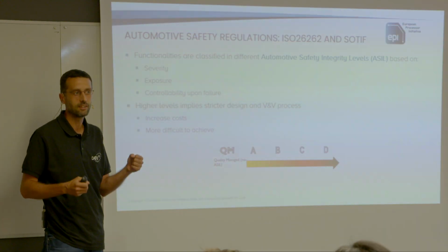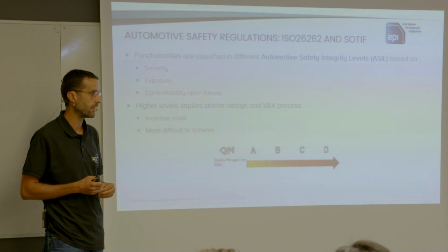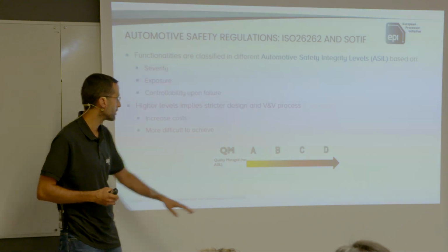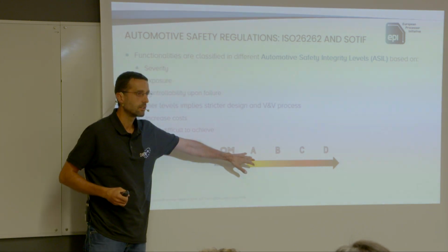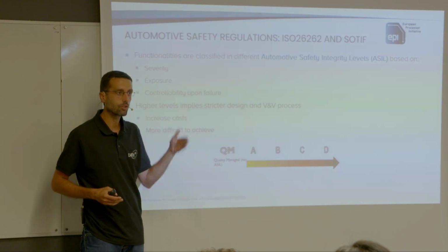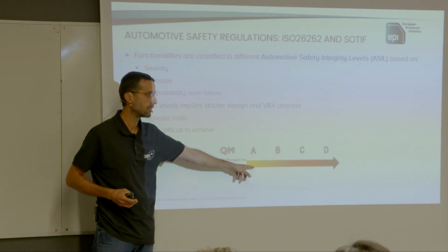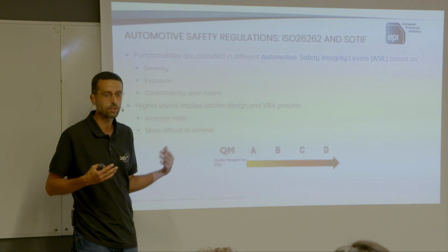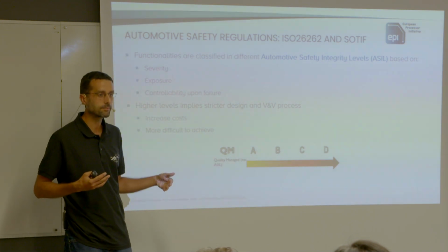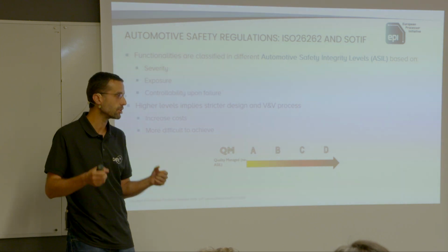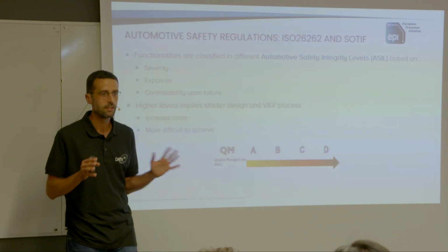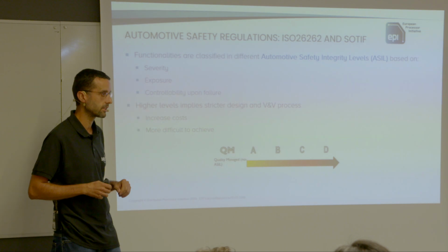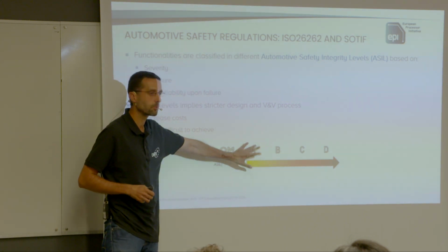The steering system is also ASIL D. But some others have lower criticality. For instance, the control of the window may be ASIL A. It has some criticality, because if you are driving with plenty of rain and the window opens, you may have some risk. You still can control the car somehow, but it may involve some problems with safety. So it's still with some criticality.